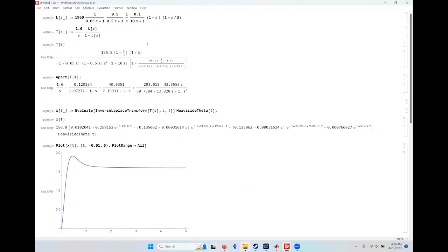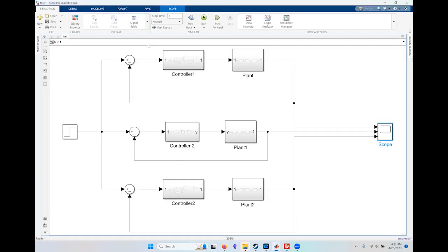Or what you could sometimes do is test a simplified system that you can solve analytically, and then compare with the analytical solution, just so that you can make sure that whatever you're doing in the simulation makes sense, right? So if you have a complicated system, you could start simulating a simplified system, just to make sure that your simulation makes sense. You know, it doesn't give you something that's problematic.